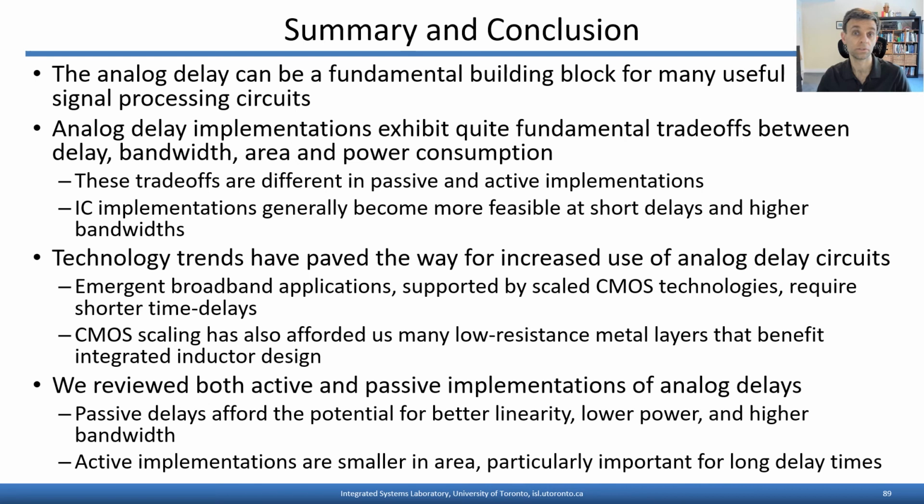I'd just like to conclude by summarizing the main points from the overall presentation. We talked about how analog delay circuits are really fundamental building blocks. They can be useful for many signal processing functions, including filtering, pipelining, and time interleaving. We also saw that analog delay circuit implementations exhibit quite fundamental trade-offs between delay, bandwidth, area, and power consumption, since those are related to the order of the delay response that we're after.